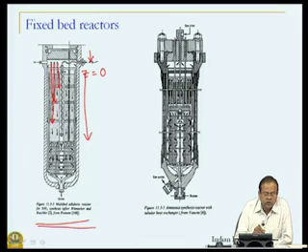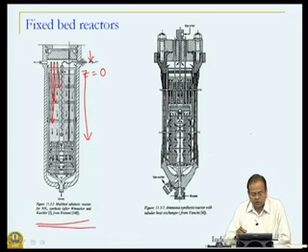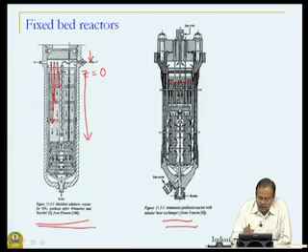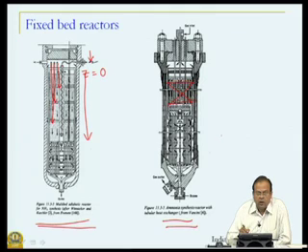So, then you premix with a fresh feed, so that temperature goes down and then thereby achieve the lowering of the temperature. Now, this second operation over here is the autothermal operation that we are going to look at in detail today. So, what is being done in this reactor is that this is our catalyst bed, but it is packed in the tubes, and surrounding this tube is a shell through which the reactant actually enters.